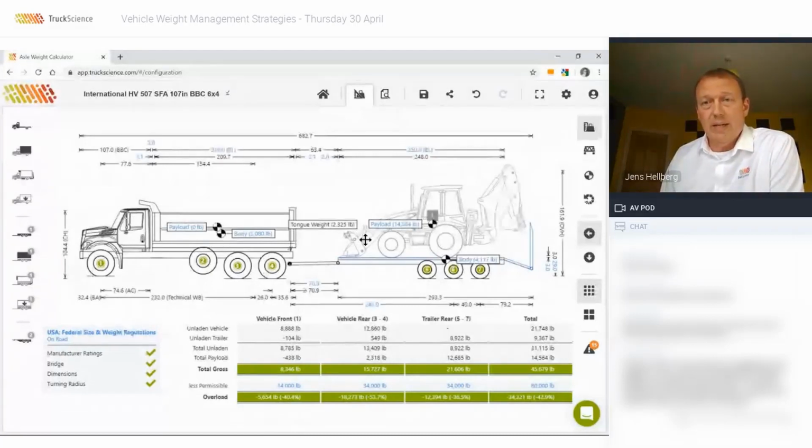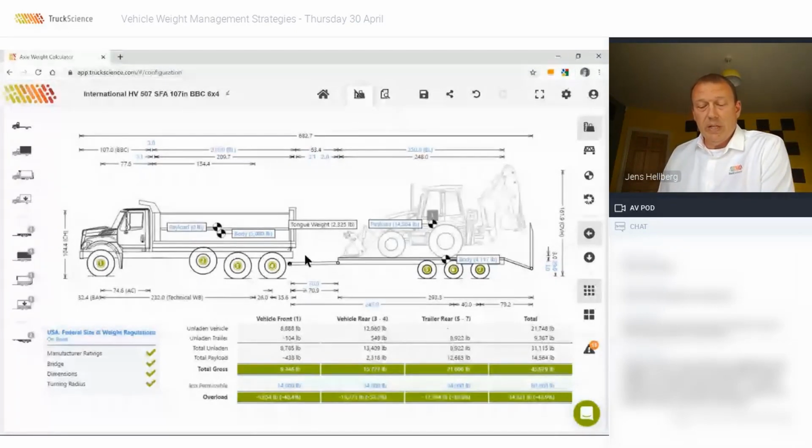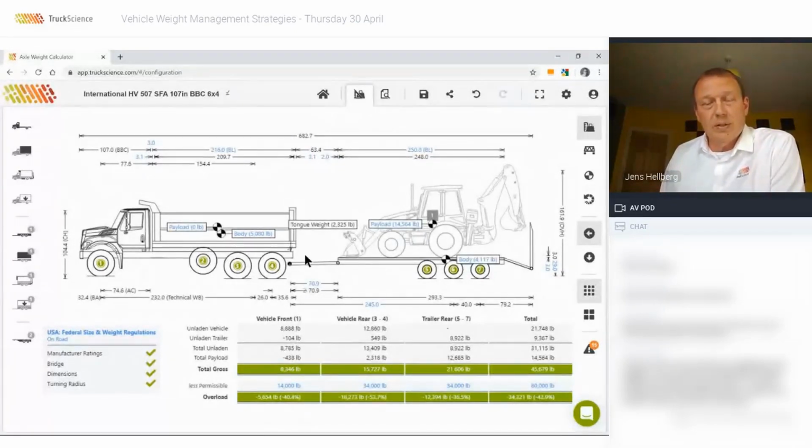So that's unladen plus payload. So in this case, the unladen is just over 9,000 and the payload about 14.5. So it's pretty much dead on 10%. So you would have to double check that with the hitch manufacturer just to make sure that the 10% is acceptable. But generally, it ensures stability of the vehicle and traction on the vehicle's driven axles and the trailer's axles.